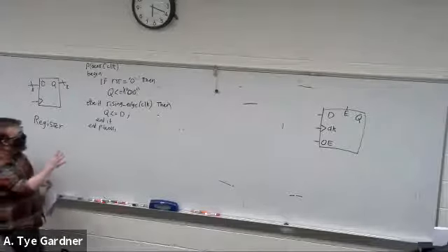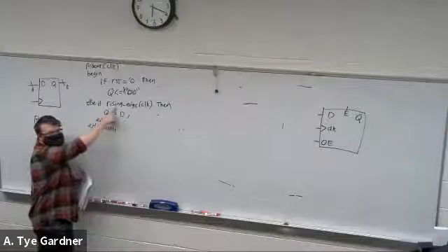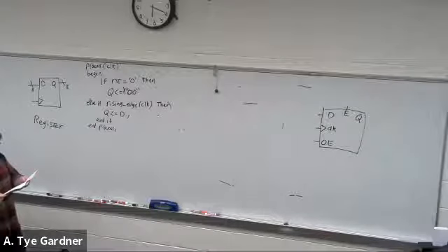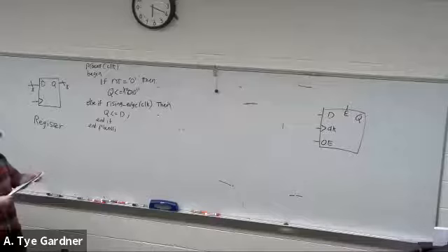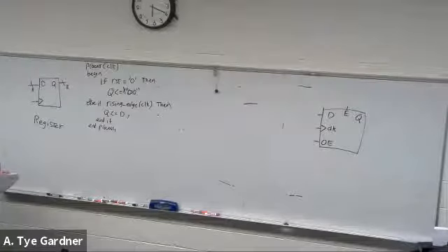I will point out, in case it's not obvious, you can also write falling edge if you'd like. So this is what we call a synchronous reset, kind of, because you can only reset on this if clock changes.